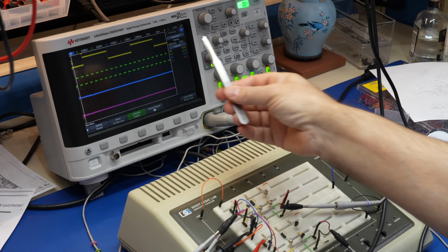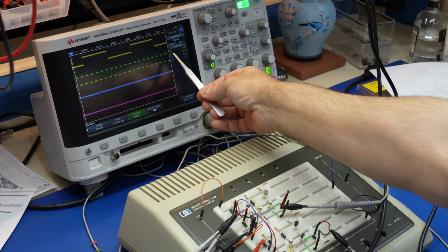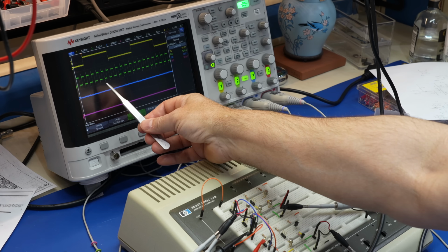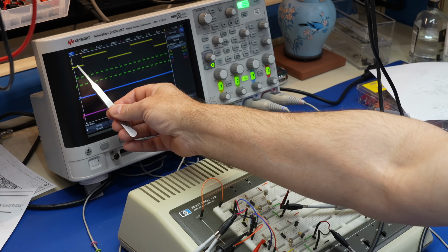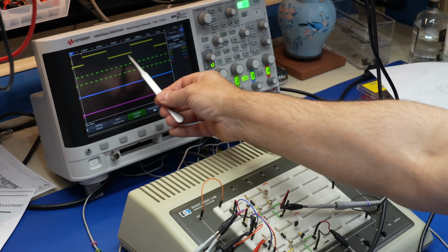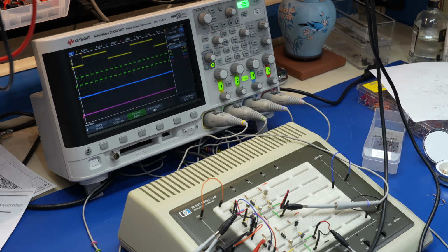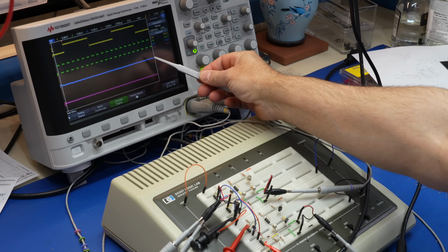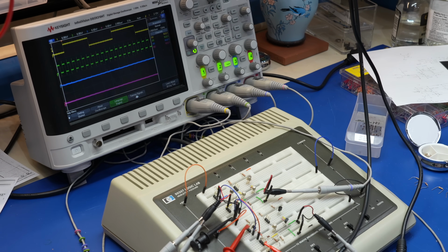I drive it with 2 inputs, 1 megahertz signal. The original gate is at 10 megahertz, so I thought 1 megahertz would be a good place to start. And I'm ending it with something that's 200 kilohertz, 5 times as slow. I am monitoring the TTL gate in blue and the DTL gate in red.